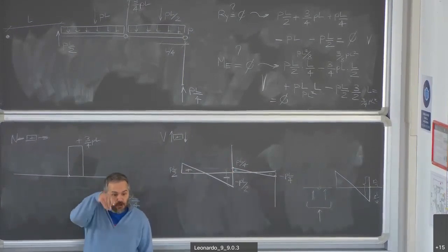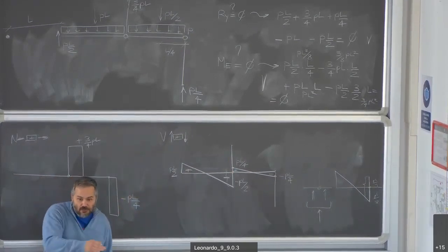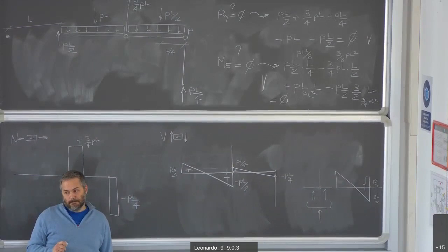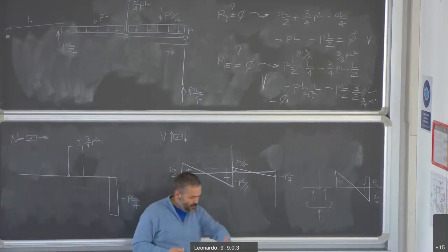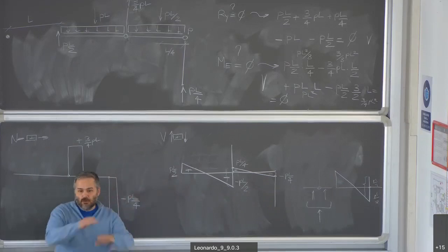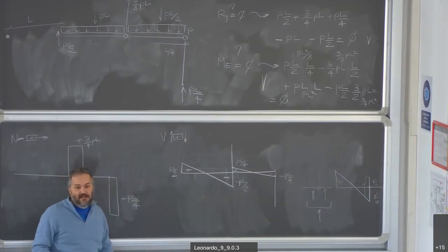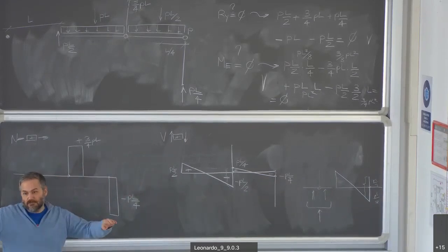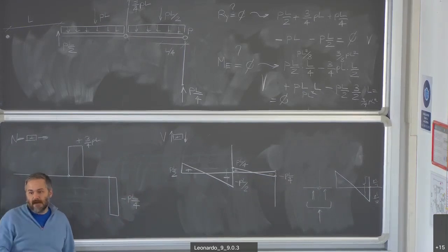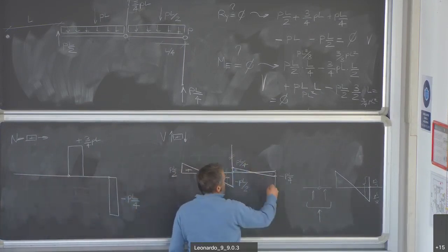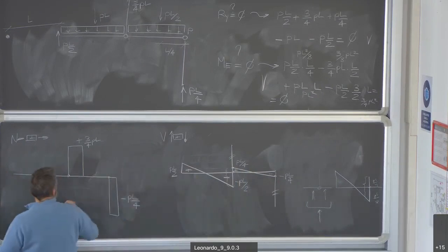The concentrated force in the tie produces a discontinuity. That is why we have that jump. This is typical, and as your colleague mentioned, you also see it in continuous beams when you have a support. But as a matter of fact, the tie we have here is nothing more than a support for the two beams. It supports, by working in tension, the two beams, prevents them from displacing, takes the forces coming from the two beams. Nothing else. This is 0, this is 0. I forgot to put it here, 0 and 0.